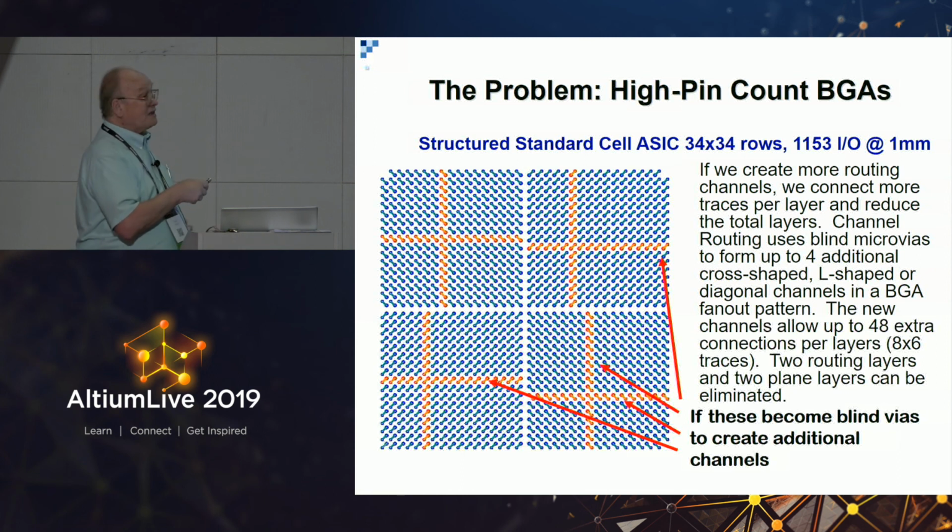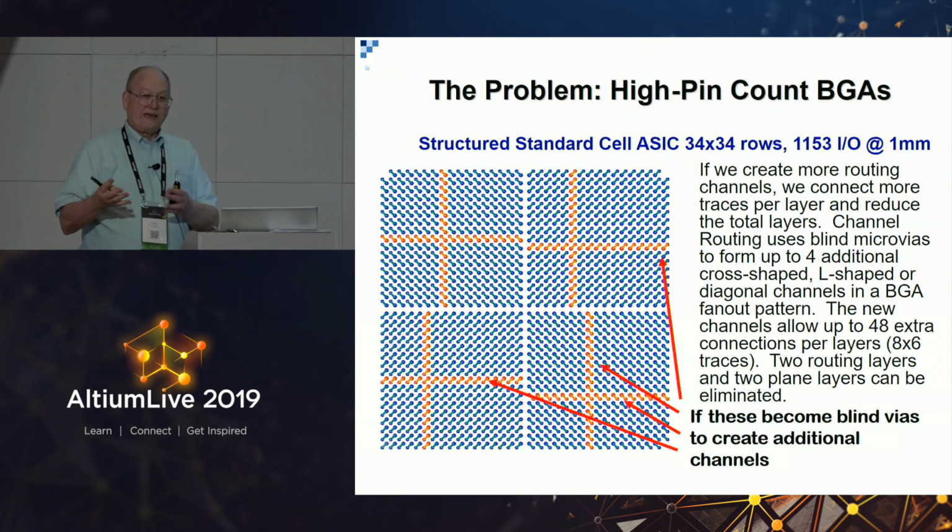So this is beginning to understand why you've got to unlearn how you did it in a multilayer. Because a multilayer with just through holes, you're restricted geometrically. Now you've added another construction element, the very, very tiny blind via. You need to rethink, how do I do breakout? And how can I take advantage of this technology, not just in breakout, but in the whole design?